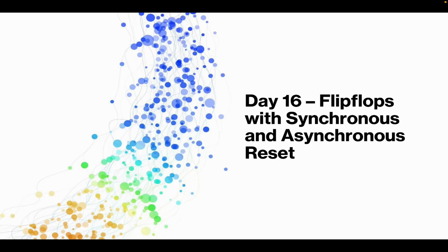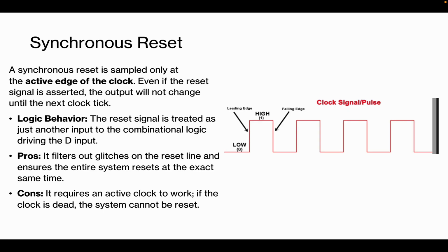In day 16 of the 100 days Verilog and digital design series, we are going to discuss today about flip-flops with synchronous and asynchronous reset. Also, we are going to discuss a very important topic, that is a reset synchronizer. It is one of the important concepts in timing analysis. Let us see, what is a synchronous reset?